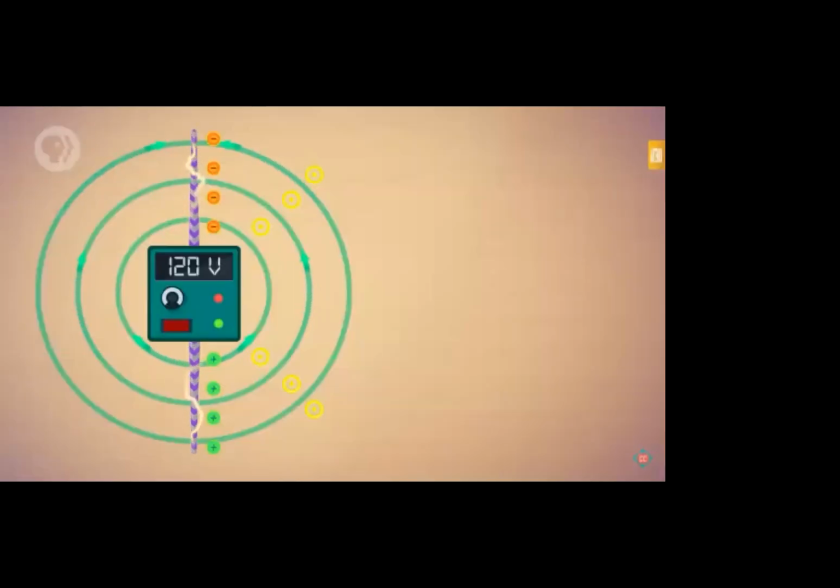The electric fields generated by the antenna itself are easier to track, since they'll just go from the positive rod to the negative rod. But as the direction of current switches, the direction of both the electric and magnetic fields change. And as the rods switch their charges, the waves generated by the initial charge distribution continue to propagate away from the antenna. So if you were standing away from the antenna, you would be able to measure an electric field and magnetic field that are both constantly changing. Now, what would that look like?